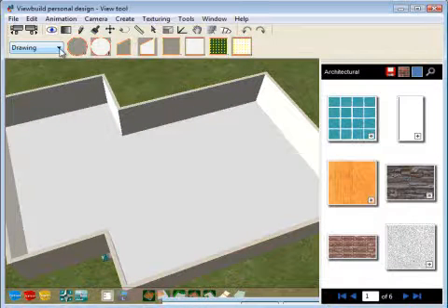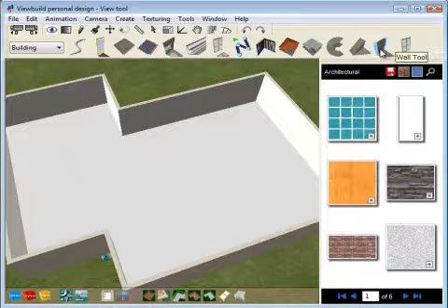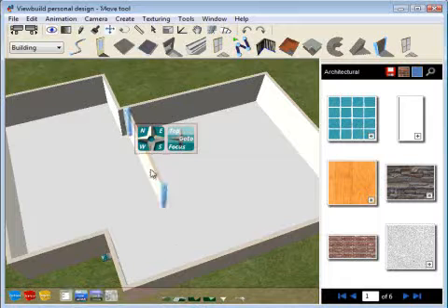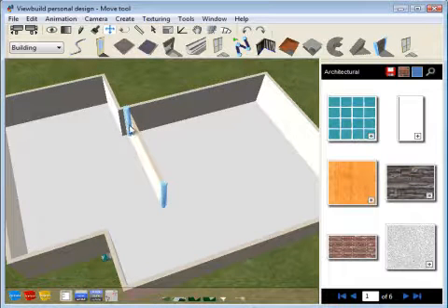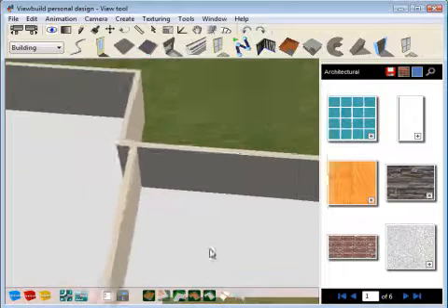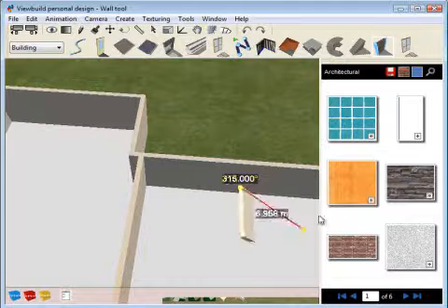Then what we're going to do is we're going to go to the building tool set, and we're going to get the wall tool, and we're going to click and drag whilst we're holding the mouse button a wall segment. Now you'll notice I'm going from the inside of the floor to the perimeter, and the reason for that is simple, that if we start there we might get that effect.